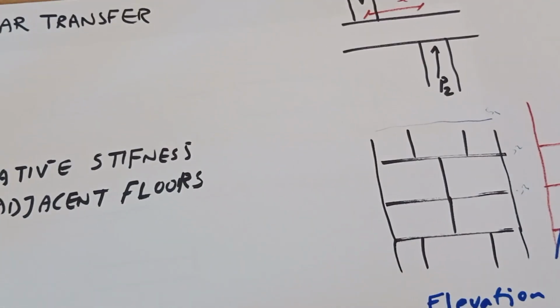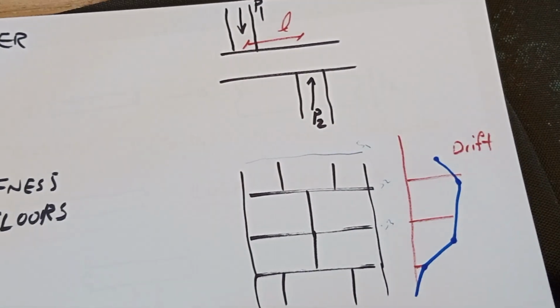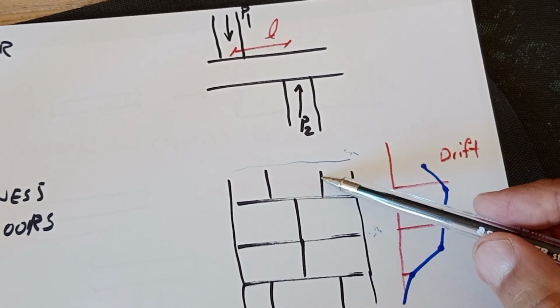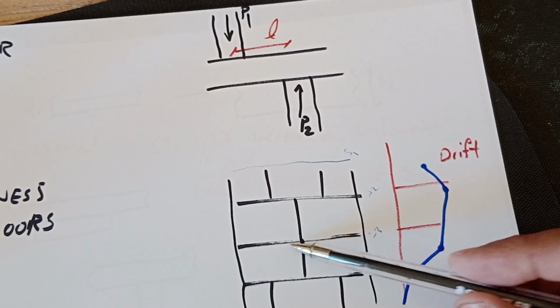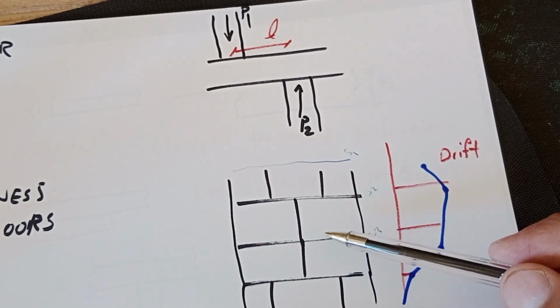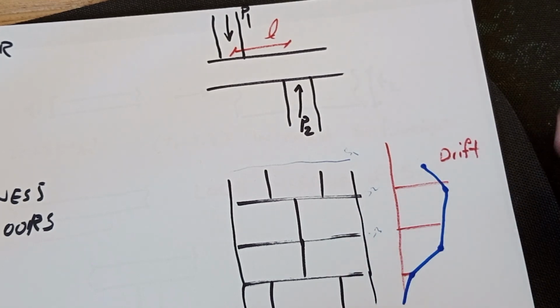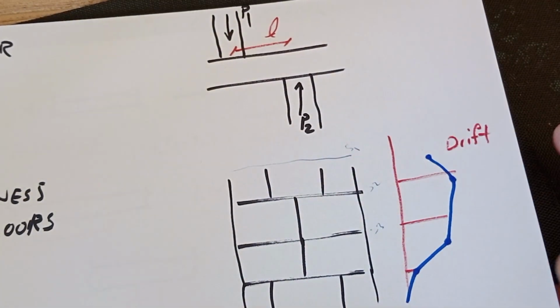And also for earthquake loading in these floors, floor up and floor down, definitely we will have a change in the distance between the mass center and the stiffness center. That's a great point in earthquake loading, and we need to care about that one.